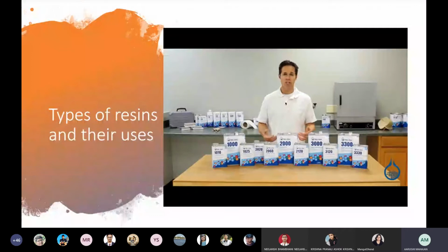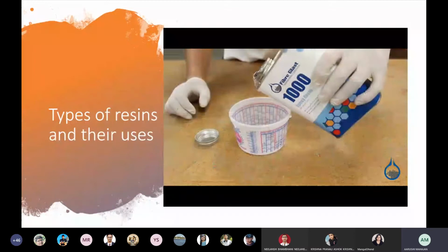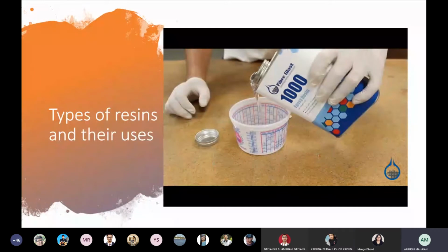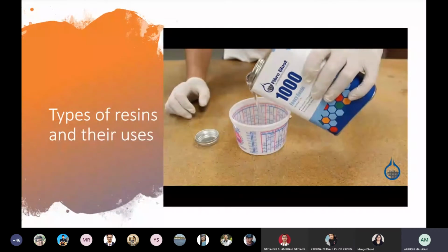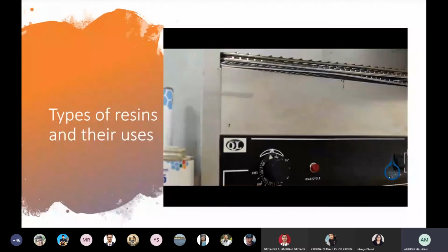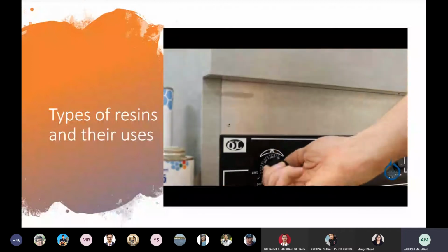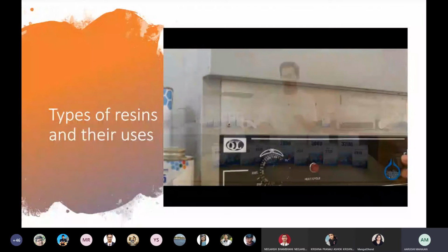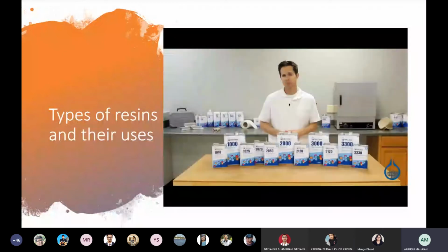Since epoxy resins bond to dissimilar materials and previously cured materials, they are a great option for repairs. Most epoxy resins can be post-cured with heat to improve their strength, service temperature, and dimensional stability. Because heat causes post-curing, parts should be cured or post-cured at a temperature that matches or exceeds their expected maximum service temperature prior to being put in service. If an epoxy part or mold is subject to a service temperature higher than it was cured, it can distort or warp.